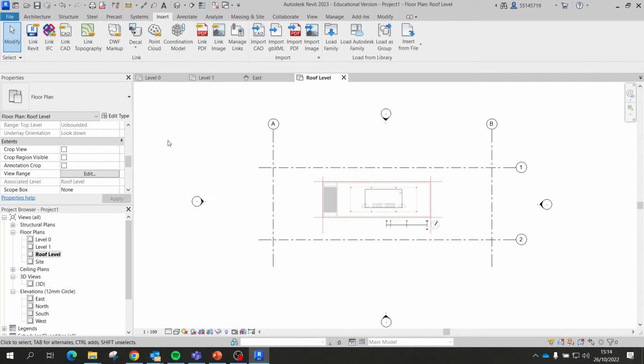Right, so if you have created a new level the way I did from scratch, this will come with some default properties attached to it. Among these properties, there is what do I see from the bottom levels, like till where do I see, right? How deep? And so you need to tweak this a bit because by default it will be set to 0. So I only see the roof level, whatever is below, I don't see it. And in that way, I can't see the grid coming from below. We build the grid at level 0.